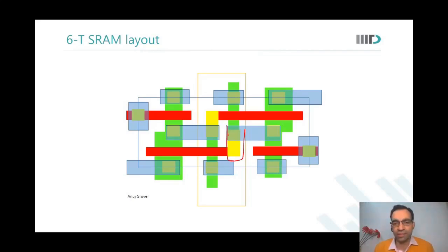That is what your DRC says, is it not? Yes, sir. We have not covered the entire contact. We are saying, instead of covering it fully, just put a small notch. Extra metal? It's not extra metal. It was the metal that was expected to cover the contact. You removed the metal from there. It is not extra metal.